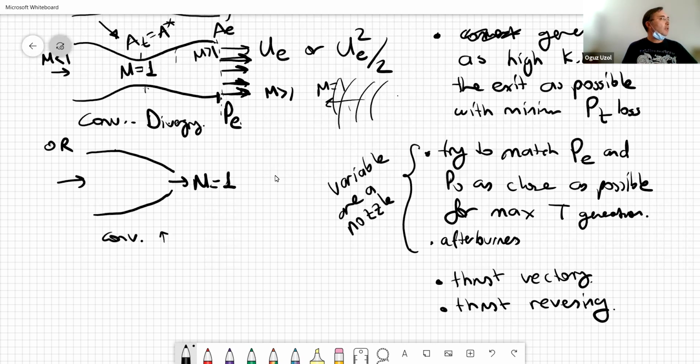Any ideas from online participants? Opening air channels into the nozzle. What? Opening air channels to the nozzle. No, that's not going to be enough. Propellant pass through the nozzle, maybe. Fluid flow around the nozzle, maybe inside. What kind of fluid? Maybe the propellant. Propellant, yes. So we cool the nozzle with fuel.